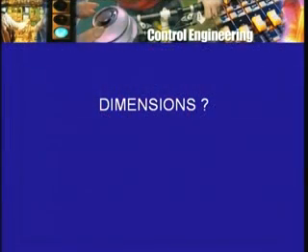Their units look different, volts per RPM or volts per radian per second, and Newton meters per ampere, but if you look at the dimensions involved, you will see that dimensionally they are the same. You should do this yourself. This will also give you some practice of looking at dimensions of physical quantities.